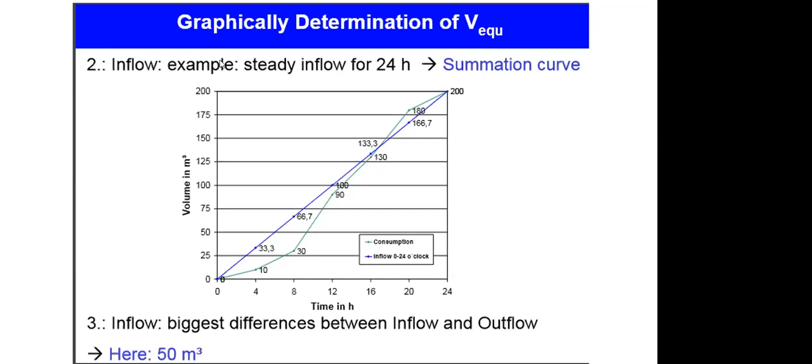Then for sizing the transmission line, that is the supply line to the pump, we can estimate like 1 or 2 hours as the operating time for the pump, meaning that in 2 hours your pump can fill the required daily volume of water.